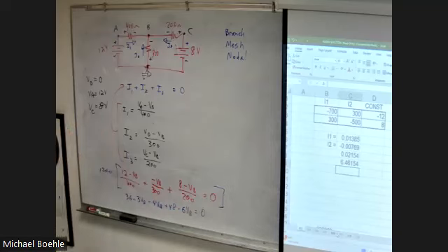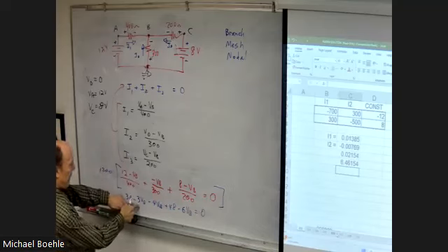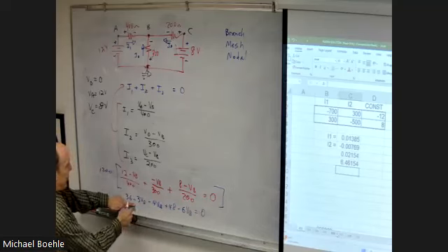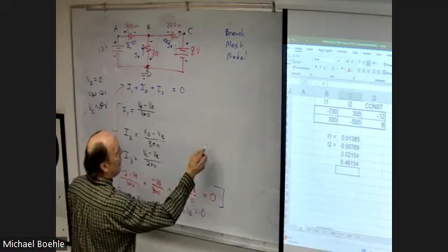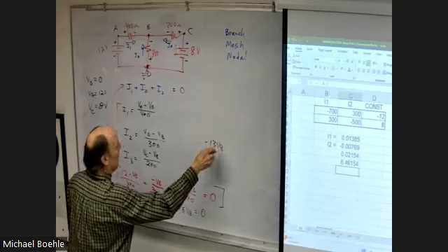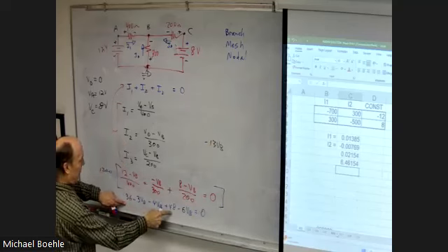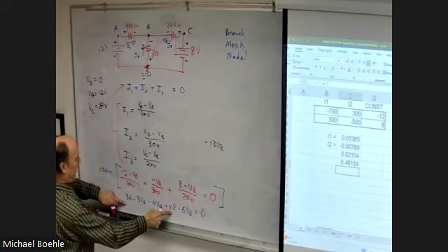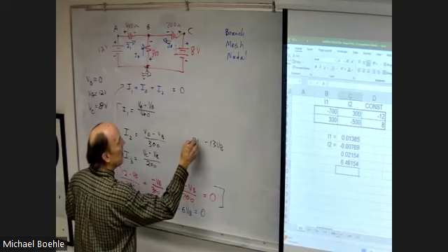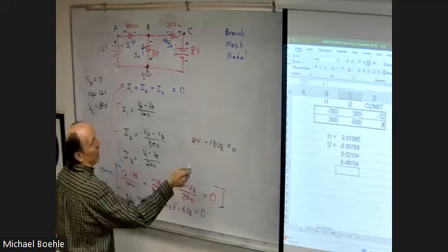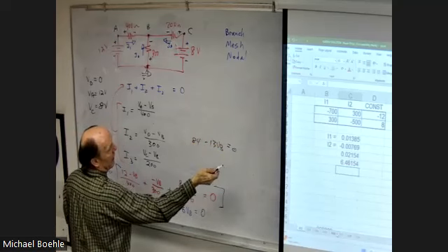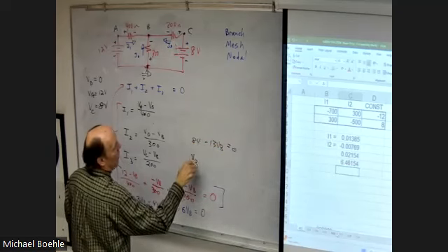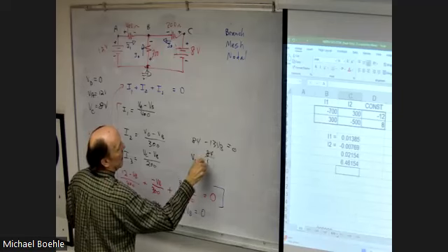0. Okay. All right. So I have a negative 3, a negative 4, and a negative 6. So that adds up to negative 13. I have 36 plus 48. That adds up to 84. So to solve this, move that to the other side, becomes positive. Voltage B will simply be 84 divided by 13.